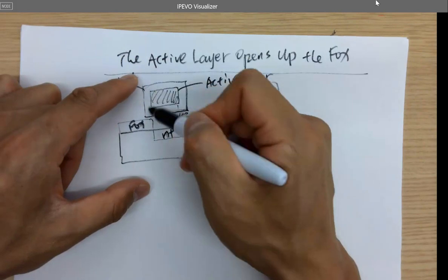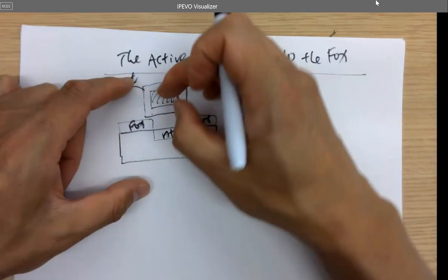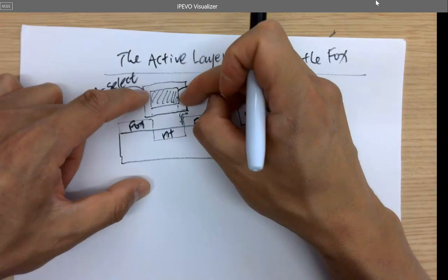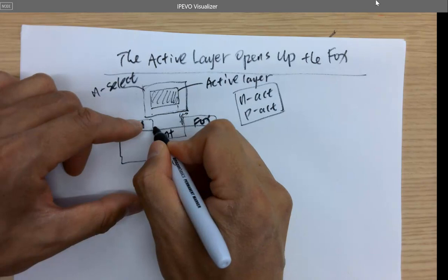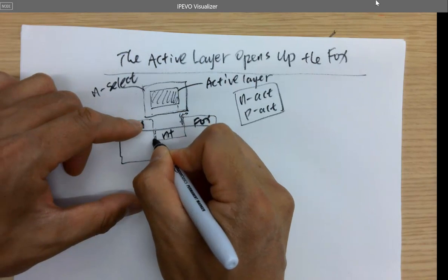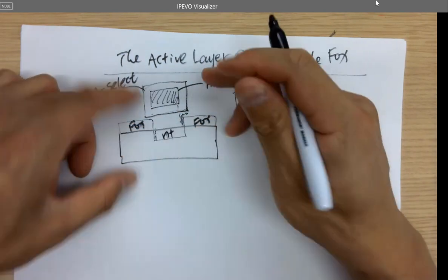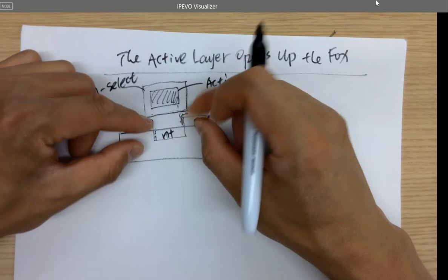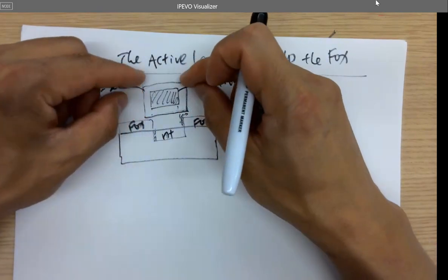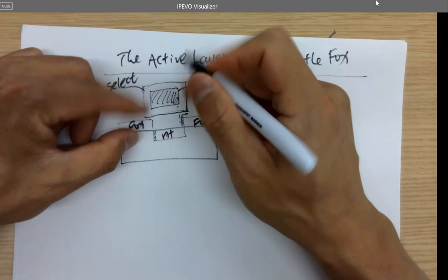These are micro or nano level dimension changes. If you make it the same size, for example, you want to align this window exactly on top of the opening, there might be a little area that will not be doped. You know what I mean? It's very difficult to align it exactly to the opening. So you would rather make it slightly bigger and start doping the material into a bigger window.